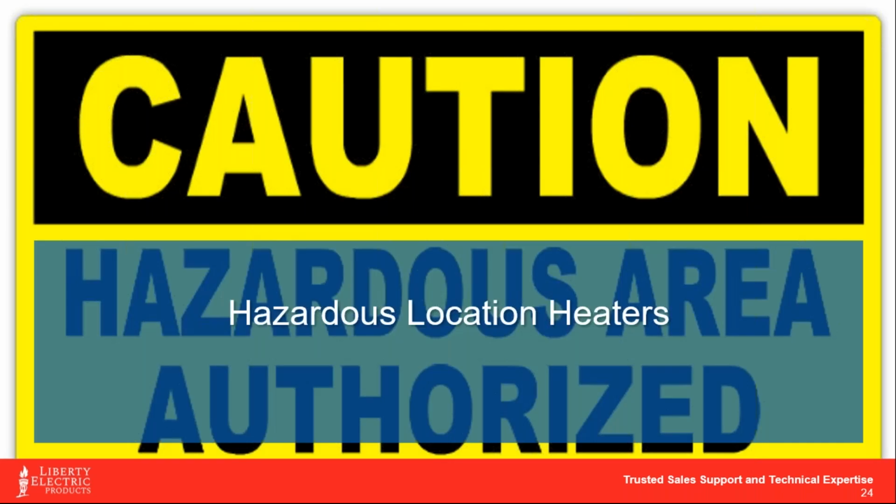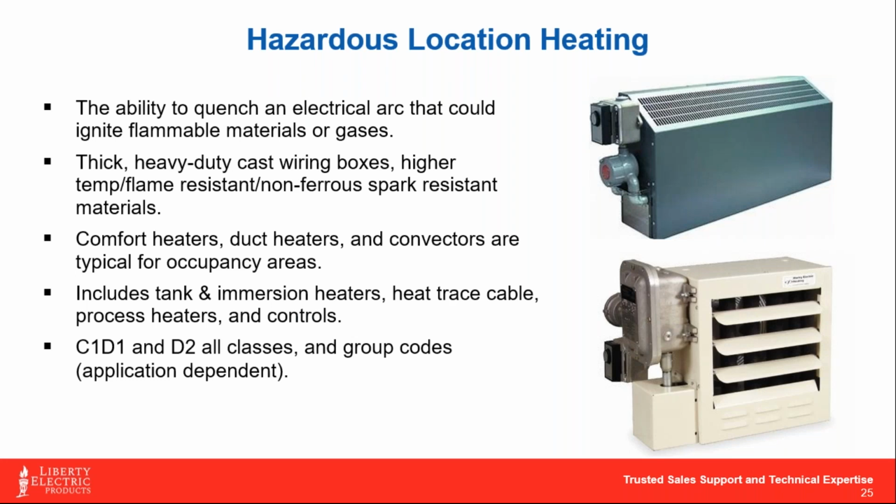Okay, so hazardous location heaters. We did touch on this a little bit with air heaters. The big gist of a hazardous location heater is the ability to quench spark at the point where we bring power to the unit. Okay, these heaters are designed with non-ferrous materials, so that we're not promoting anything that can create a spark, because hazardous location heaters are typically used in areas where you've got combustibles. So it's not that common, in the case of, say, something like rubber or plastics forming. But if you get out onto a gas compressor site, that's a whole different story, and everything is going to be hazardous location rated. So again, this is just versatility of the equipment itself, in that it can be done, and it can be done safely.